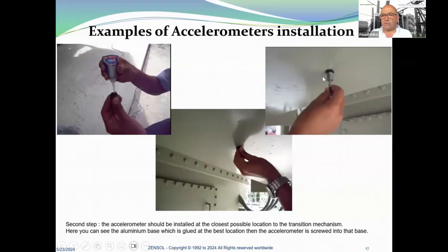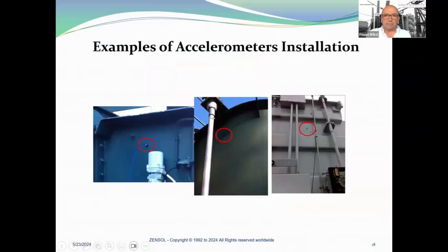And for your information, this aluminum base stays there for 1 year, 2 years, 3 years, 10 years. We do not remove it, because this way, the next time we come to do a recording, we have nothing to do, just screw the accelerometer at the same location.